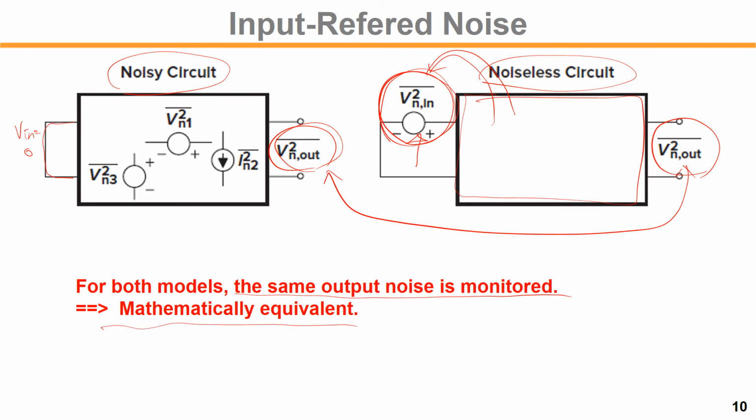So our question, or work to do, is to find this input reference noise that captures all the inside circuit noise, right?